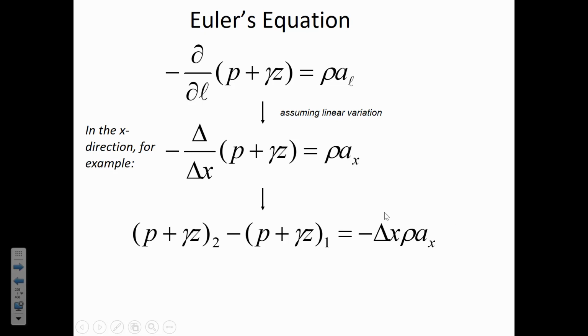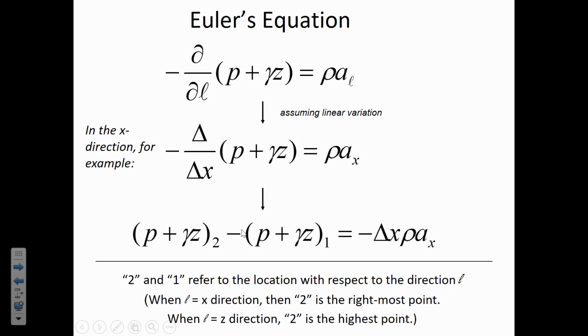So here's in the x direction. Yesterday I sent an email that had what Euler's equation looks like when you apply it in the z direction. So if there's vertical acceleration, that simply means that acceleration is in z. The distance between the 2 points would be a delta z instead of delta x, but then nothing changes on the left side of the equation.